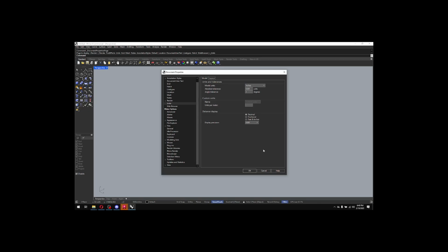Architects tend to also draft in inches. If you run into a Euro, they're going to be drafting in millimeters. That's just how it goes. So get used to sort of converting things. What's nice about Rhino that AutoCAD cannot do is, as you saw, I was in millimeters, but I was typing everything in feet. It will make those connections. You don't have to be in certain units.